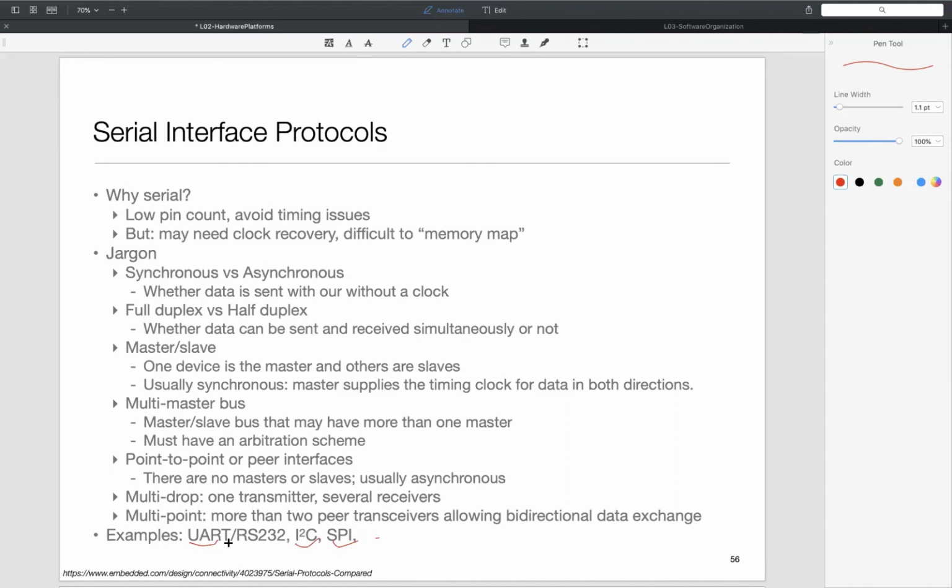Anyone know the difference between UART and RS-232? I'm sure you have encountered both these terms for serial ports. UART is the basic serial communication protocol, which is very common when you see bit rate on the modem and all. RS-232 is a specific voltage standard on top of it.